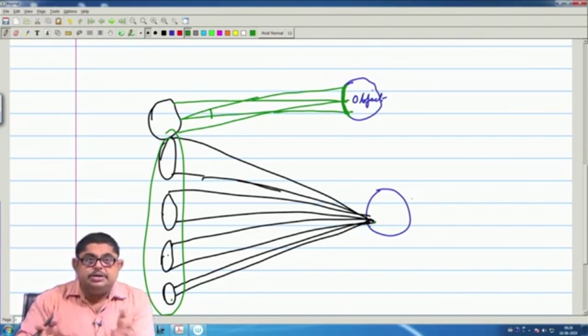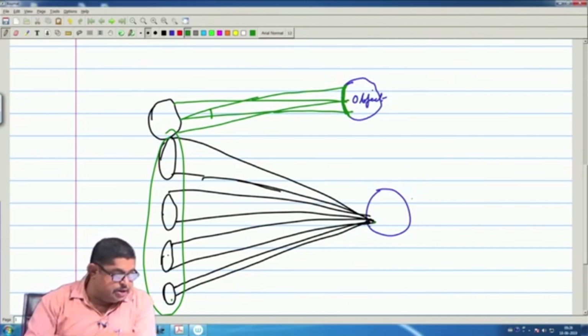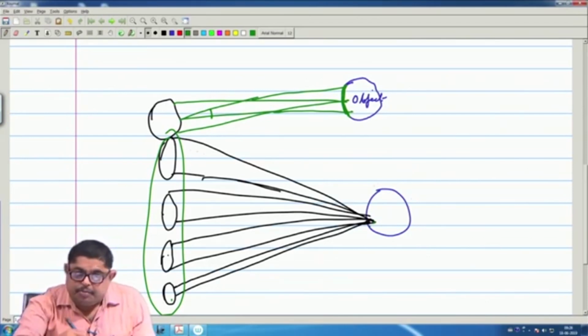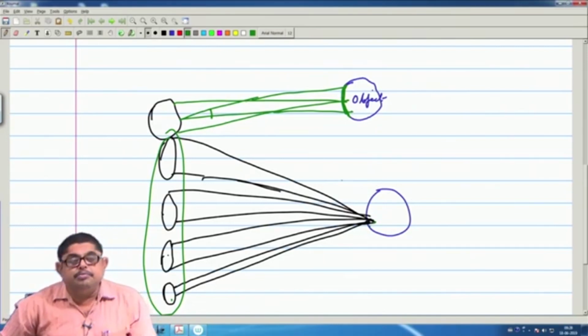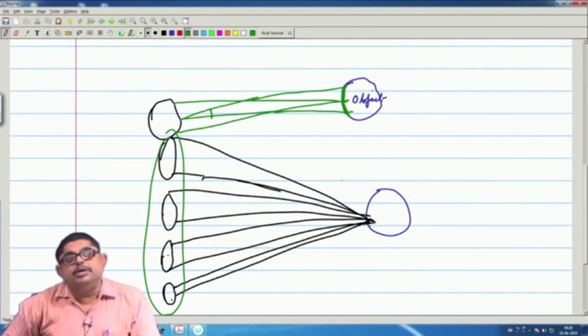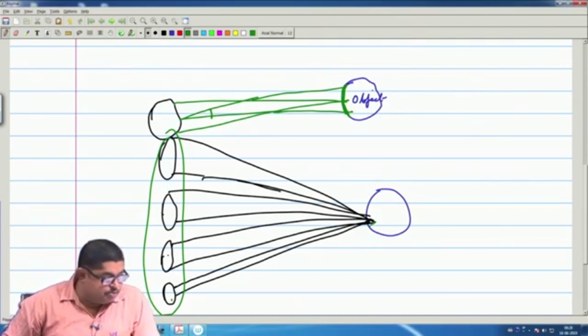Actually, with this phase compensation only returns from this point are constructively added, but obviously when it is illuminating from here, these other portions also will send the return, but in the phase compensation they are removed because we are looking only at this point, or the whole SAR processor is focusing on this point. So, returns from others are removed.